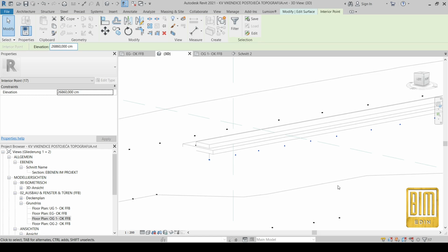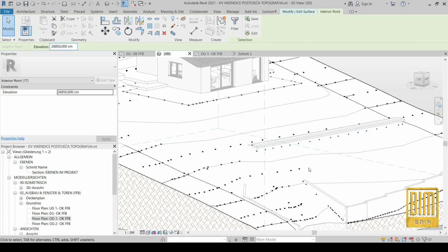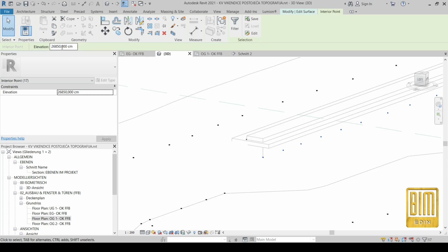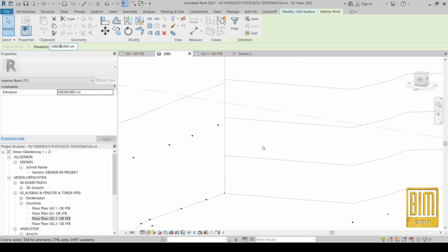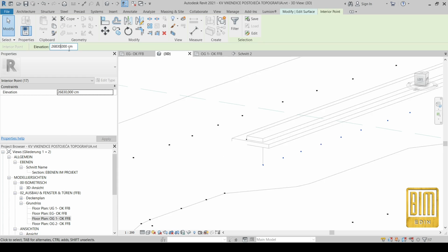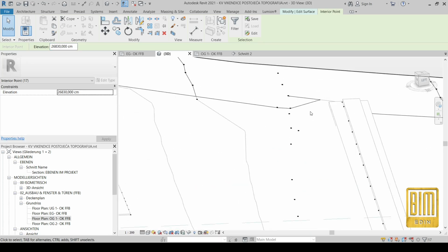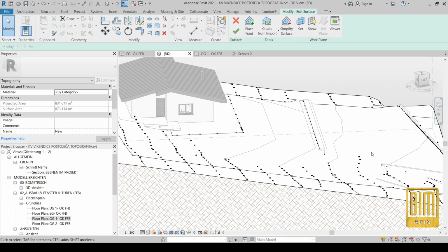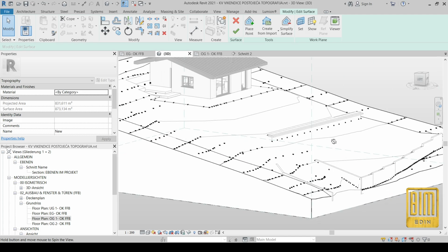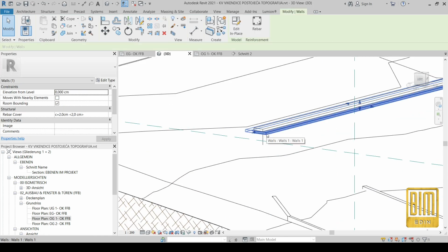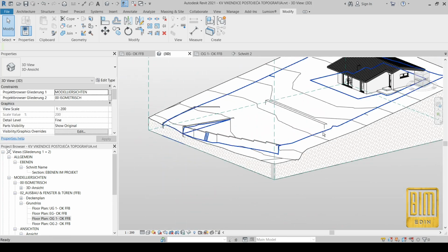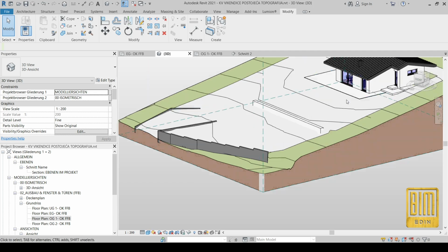All right, as you can see, I place the points to other side, I select them, and I will change the height of these points from below side of this gabion wall. All right, this is it. The topography points on other side of gabion wall are 50 centimeters lower than topography points from below side of the gabion wall, and that's it.